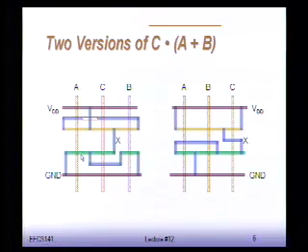So in this first case, what you do is you say, I'm going to lay out, from the left to the right, first A, okay? So the source of A, we know is grounded, so that's easy. Then we know that the drain of A has to be tied to the source of C, okay? So if I now decide that the middle gate is the gate of C, this has to be the common node, okay?